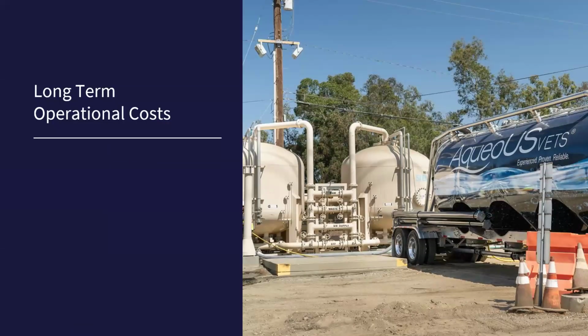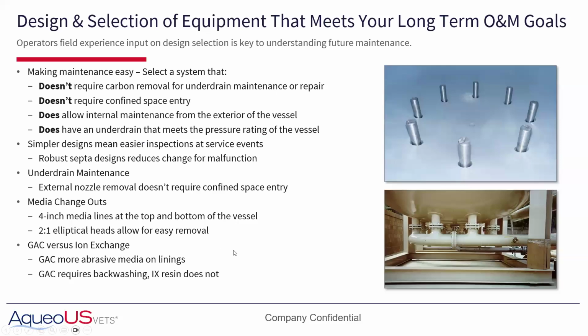So the long-term costs. Different designs, again, you have to take into account what this long-term cost is going to be. The external ring header design here, you have the ability to drop that system down on a pallet jack and be able to inspect the nozzle, so you don't have to enter the system. It allows for internal inspection from the outside of the vessel. So it has the under drain. It meets all the pressure vessel ratings of a vessel as well.